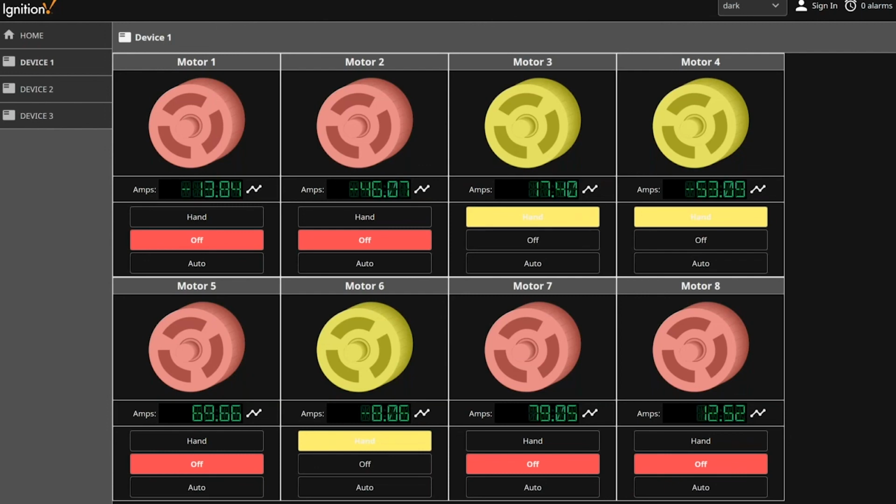I could have up to 8 motors, so I'm going to create 8 instances in my definition of a motor UDT, but I then dynamically check how many motors actually exist, and then I disable the ones that don't exist for that instance. So no, you can't really just add or remove tags inside a UDT, but you certainly can still accomplish that by doing it in a folder structure, or by just having the max number of tags and then disabling the ones you're not using.